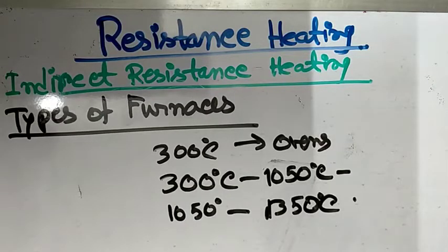First, the life of the furnace lining is longer, as intense local temperature of the electrical arc is avoided. Second, due to even temperature distribution, heavy loss of volatile elements, such as zinc in brasses, is avoided. Third, it has better power factor, resulting in a lower electrical bill. And fourth, there is no noise due to arc.